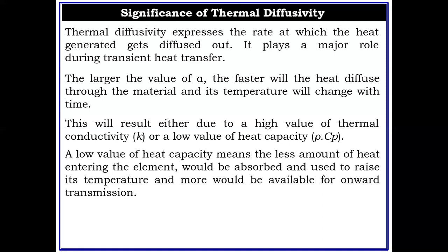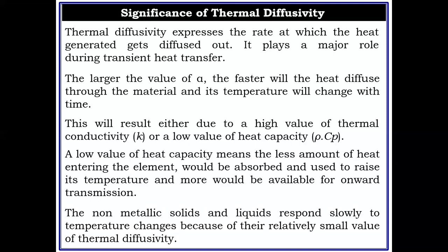In short, whatever the heat transfer into the element, if thermal diffusivity is less, then maximum heat will remain inside only and will not transfer to the second side, because thermal diffusivity is less. Non-metallic solids and liquids respond slowly to temperature change because of their relatively small value of thermal diffusivity.